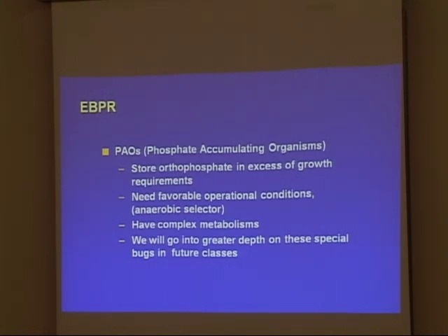They need favorable operational conditions. You've got to have an anaerobic selector. So that means A, B, and C have to be operated anaerobic. Now we're talking no DO, no nitrate, anaerobic, and just basically running those mixers up there to keep everything in suspension. They have complex metabolisms.